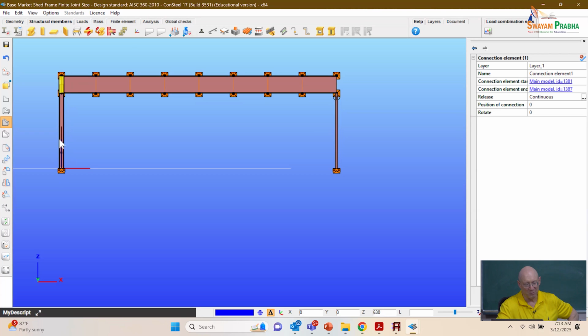I'm not going to model member length all the way to that center line. We've got a big honking beam adjacent to the center line over a finite length there of the panel zone. So that's really a more realistic assessment in terms of sizing the column.